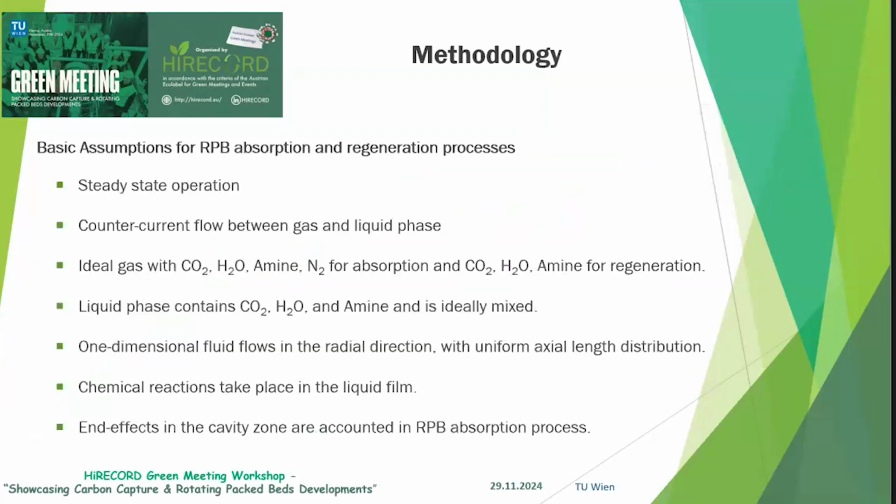Of course, every modeling method has some basic assumptions. We have assumptions for both the absorption and the regeneration. At this point, we operate at steady state with a counter-current flow arrangement, and an ideal gas phase assumption with CO2, water, the amine and nitrogen in the absorption. A critical assumption is that chemical reactions take place in the liquid film, and this is the part where we address this phenomenon. Also, end effects in the cavity zone are accounted for in the absorption process.